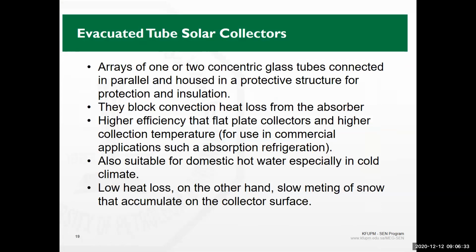Evacuated tube solar collectors, on the other hand, are another kind of application. Why evacuated tube? This is basically made up of a double layer of glass, and this double layer of glass has evacuation in the middle, so there's vacuum between them. Glass is going to transmit the solar energy anyway, so the energy is going to penetrate whether it is one layer or two layers of glass. Solar energy can penetrate in a medium, or can it penetrate in vacuum? So it will penetrate through the glass anyway.